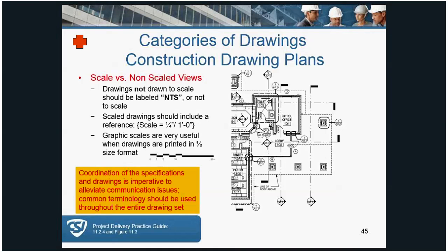Note that although commonly accepted as a practice, there should not be a defined order of hierarchy in drawings. For example, stating that larger scale drawings take precedence over smaller scale drawings. If the drawings are complementary, then they all work together, and what is required by one is required by all. If there is a conflict, then a question must be asked to clarify the design intent.